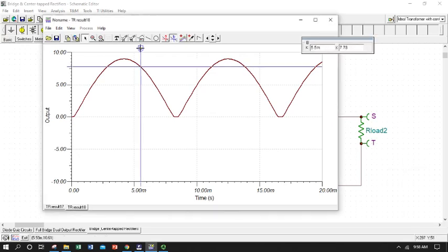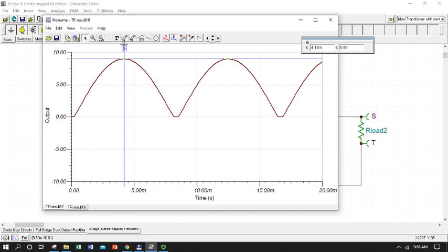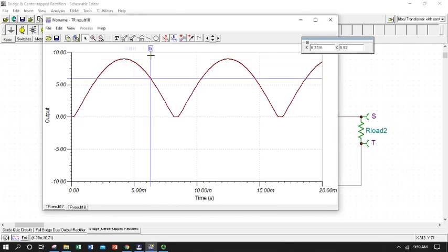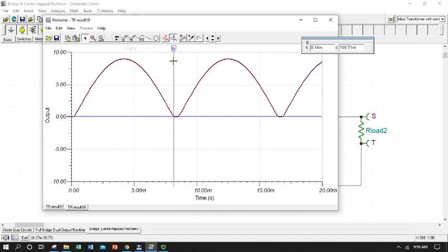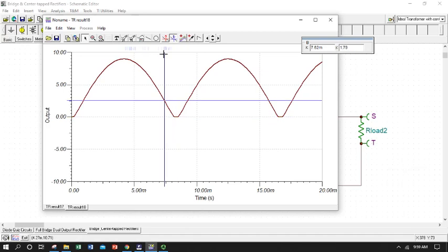I should be able to now see the influence of both diodes being dropped. So now we're just at 9. So we said each diode forward bias was dropping about 0.5. Given that we had 10 volts coming out of our transformer secondary, we can see that we've dropped the effect of 2 forward bias voltages. So 0.5 and 0.5 is 1. We're now seeing a peak voltage of 9 instead of 10. And then we are seeing that same effect down here at these little plateaus where the diode forward bias basically cuts the signal off a little bit between.